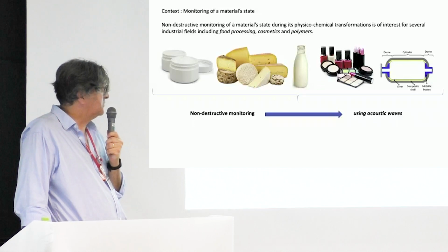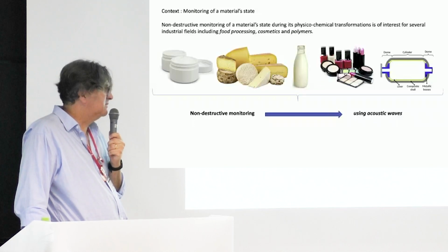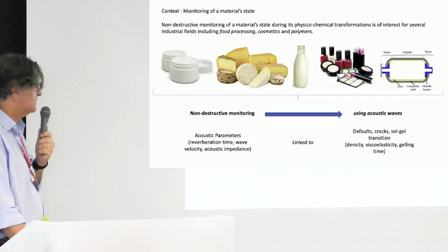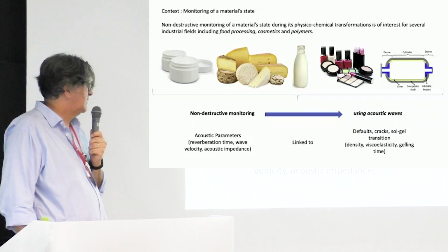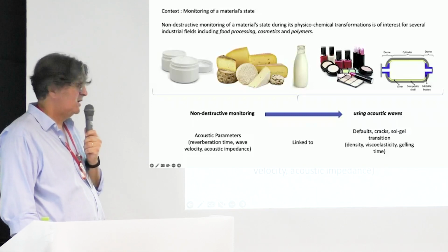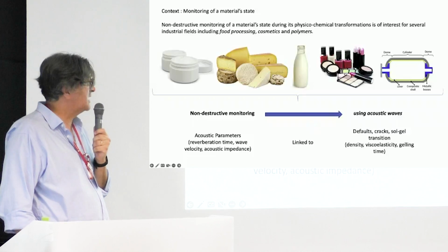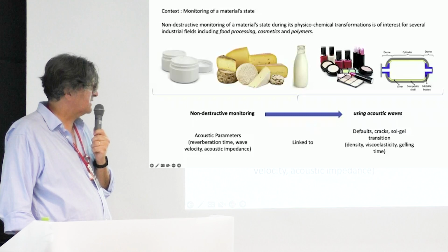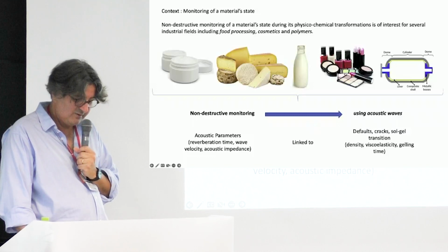So a non-destructive technique is, of course, a powerful tool. We know that. And we can have some acoustic parameters, such as the wave velocity, the acoustic impedance, the attenuation, but also the reverberation times in such structures that are linked to defects, to cracks, to transitions, and so on.